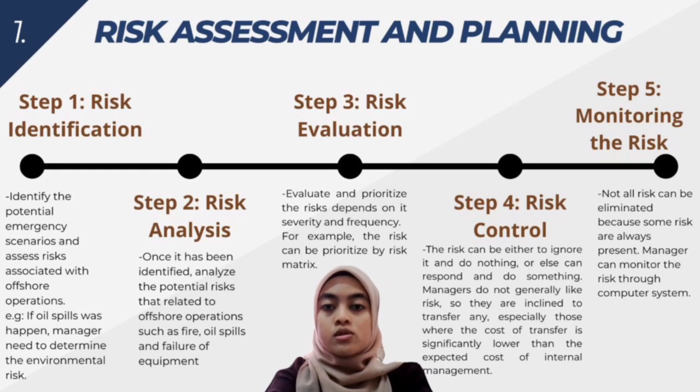Step 2, risk analysis. Once it has been identified, analyze the potential risks related to offshore operation such as fire, oil spills, and failure of equipment. Step 3, risk evaluation. Evaluate and prioritize the risk depending on its severity and frequency. For example, the risk can be prioritized by a risk matrix.